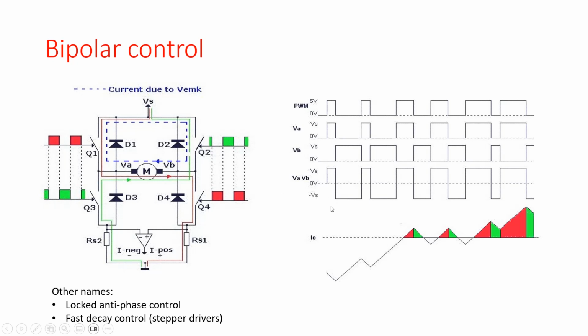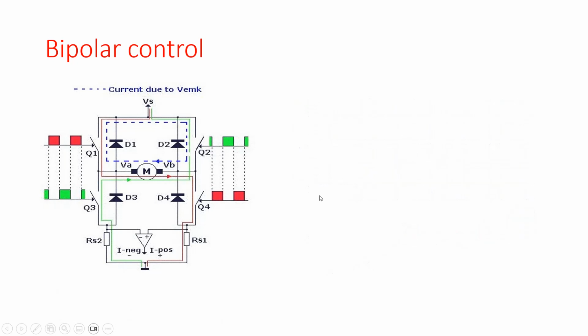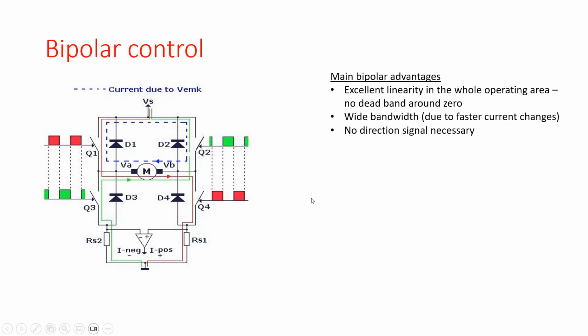That could be a potential safety issue, because when, for instance, the connection for PWM from your CPU or your I/O board towards the amplifier is lost, then the PWM value is 0, but in that case there is a maximum voltage across the motor, and in that situation unpredicted things can happen, so be aware of that. So let's look at all the properties of the bipolar control.